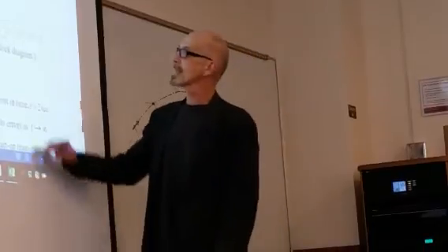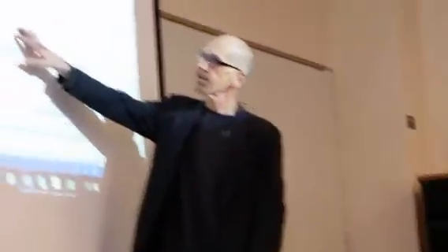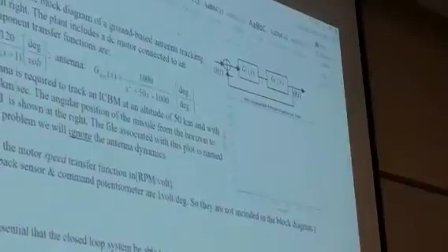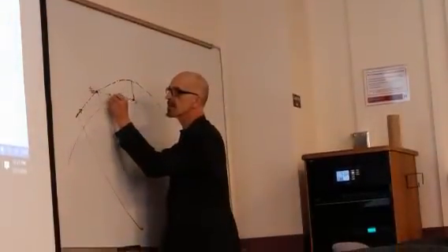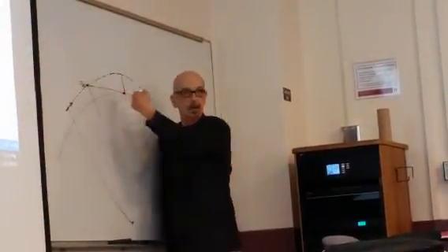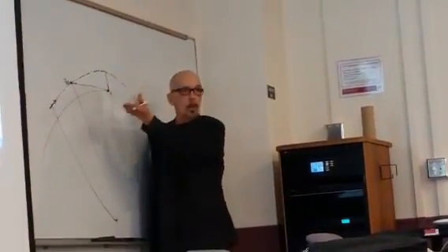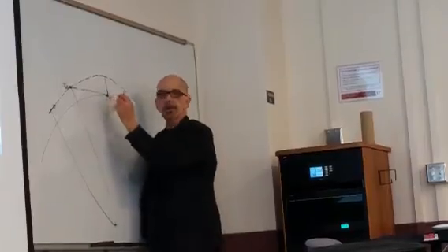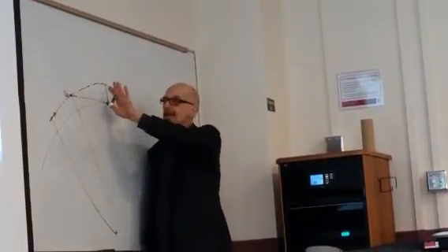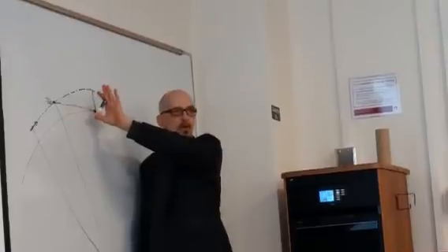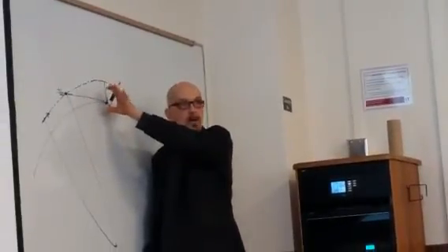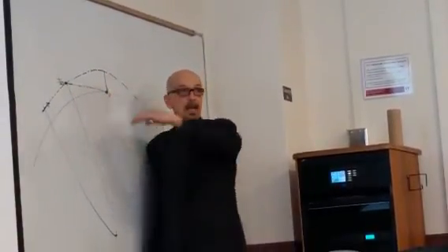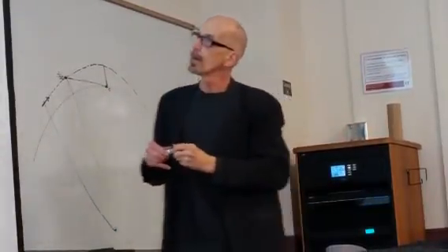For the ICBM, this is the apparent degrees. What do I mean by the apparent degrees? Well, this is what happens at time 0. At time 0, this thing is coming mainly in, correct? So it has a very low apparent angular velocity relative to point P. That antenna can just pretty much stay where it is, maybe tweak a little bit up or down, but then as it gets overhead, it's going, right? So this is what the angular displacement of the antenna does over time.